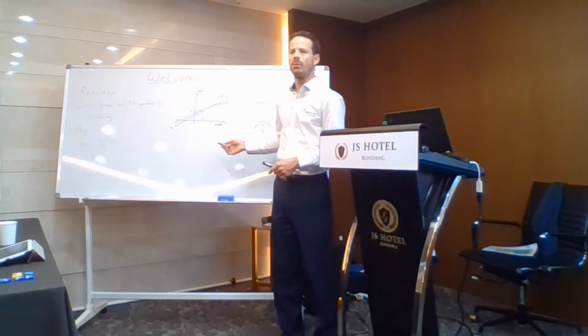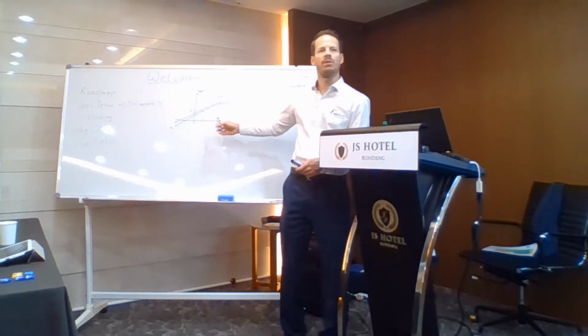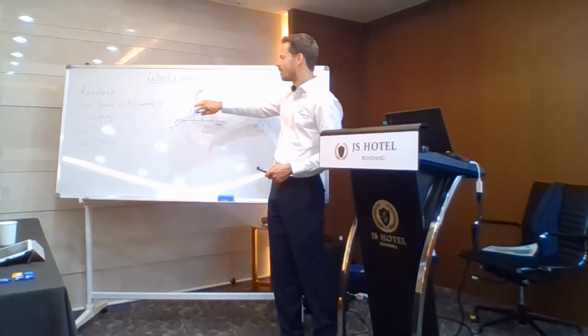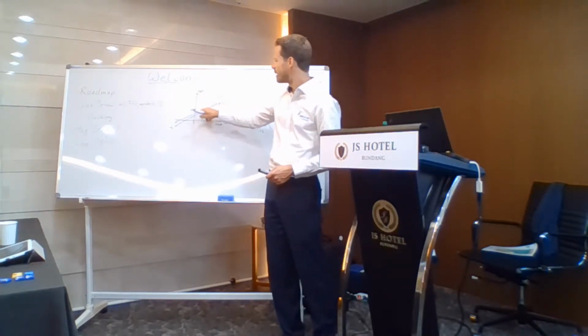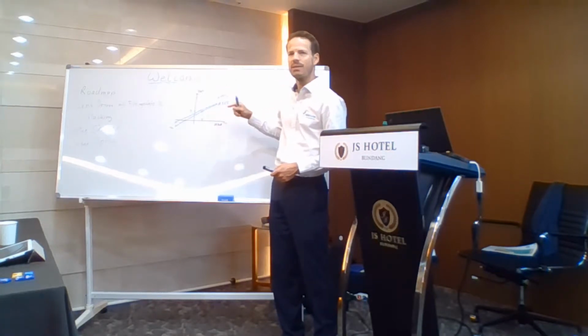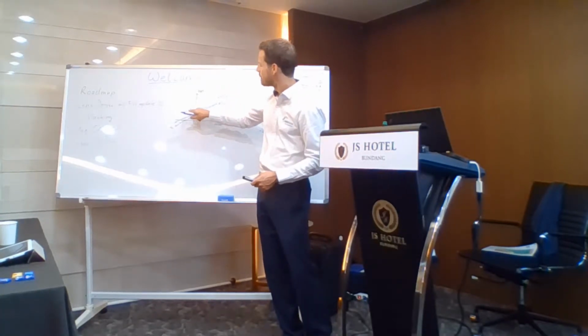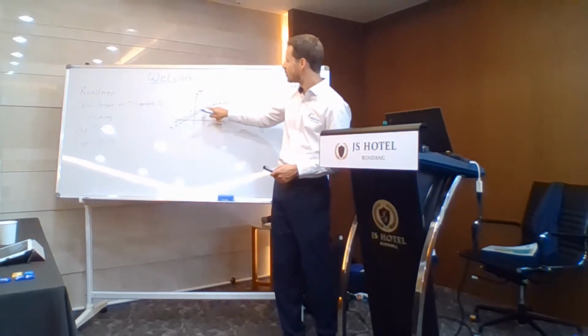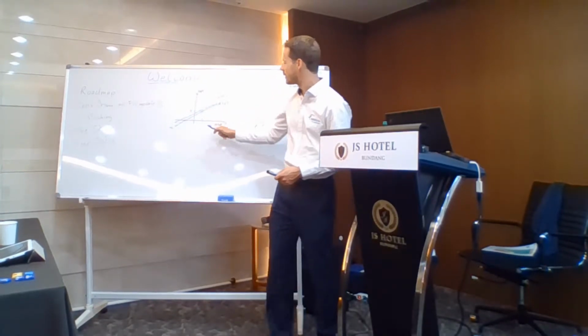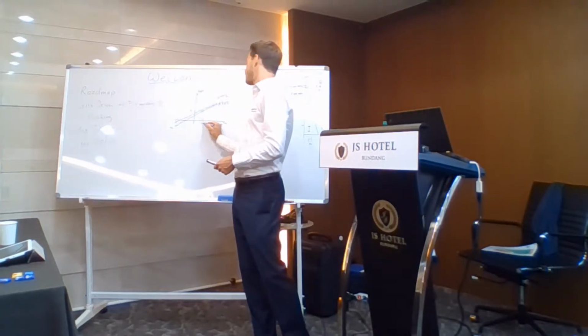Okay, so we will not discuss the calculation, but based on the calibration data and the temperature that we can read from the lens, if somebody wants to go to a specific optical power, the driver will calculate what current we have to output, maybe 75 milliamps.